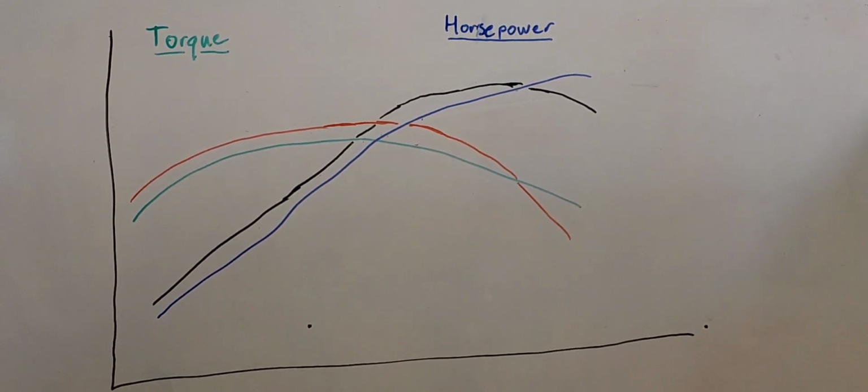However, because every engine is ultimately air starved, we get to the point where the cylinder heads can no longer flow the air, and they simply become a restriction. The energy required to get the air into the cylinders is no longer less than the energy that is being trapped. That is when brake mean effective pressure begins to fall away.